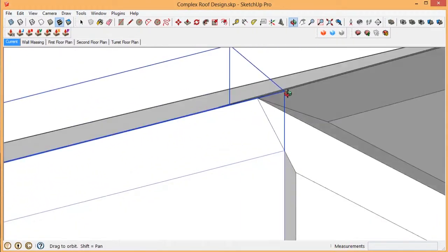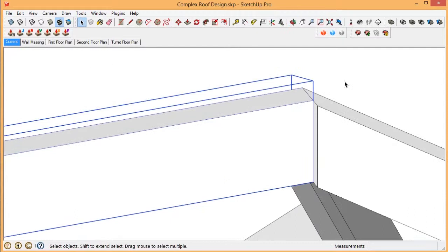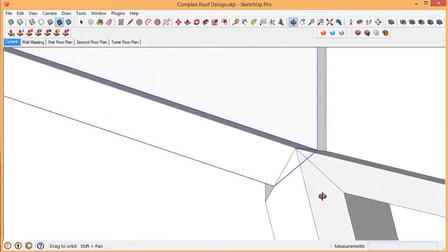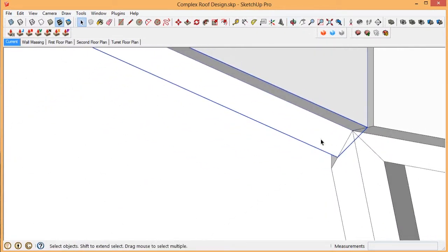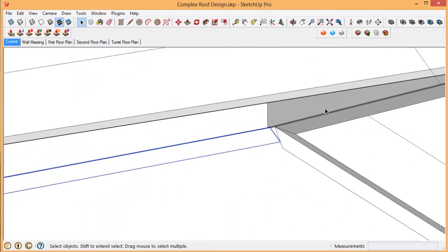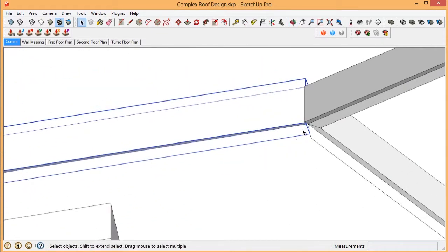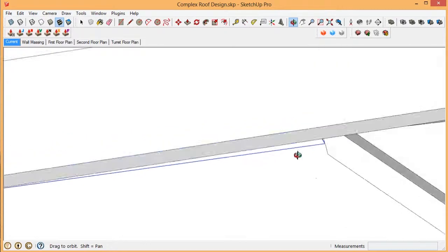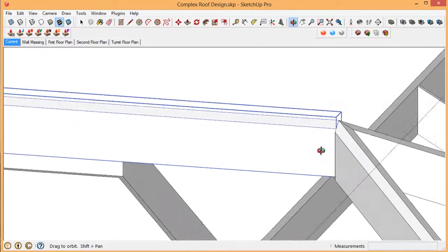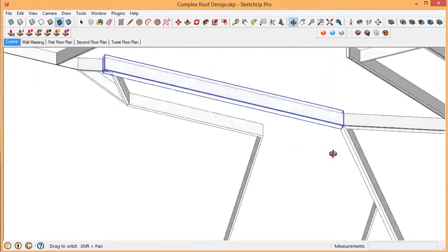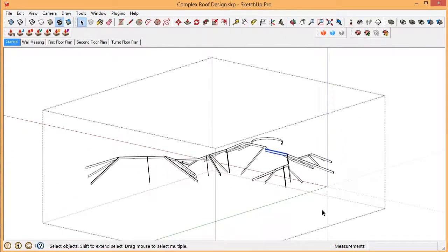We now have skeleton members that are very well defined both on the top and lower faces, which is something that you may not want. If this is just going to be a rough framing job, then the bottom of the ridges, bottom of the hips and valleys might just be straight dimensional lumber. So if you want to take the extra step to edit these, I'll show you how to do it.